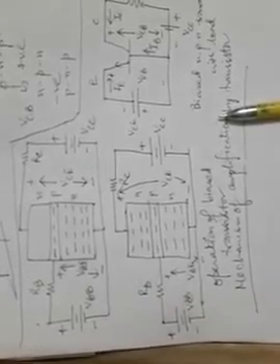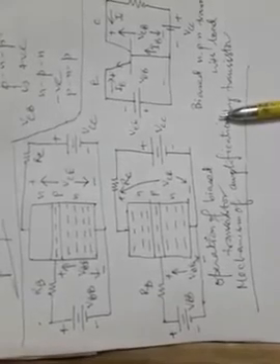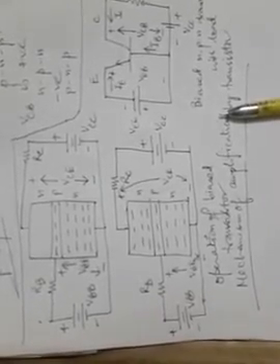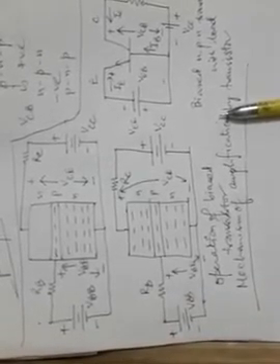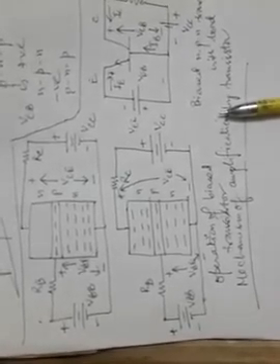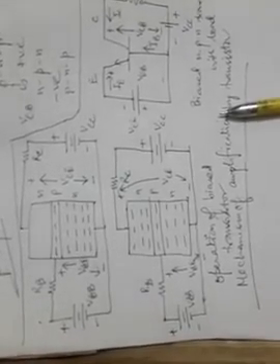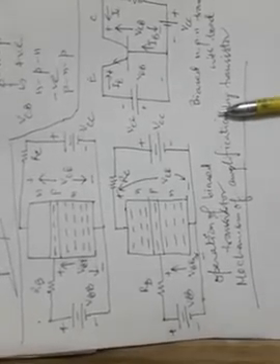Now the forward biasing of the emitter base junction will permit a large number of electrons to be injected from the emitter side into the base side. Because of high doping of the emitter, the conductivity of the emitter is much larger than that of the base, and because of the light doping and low conductivity of the base region, a very small number of holes will flow from the base into the emitter side.